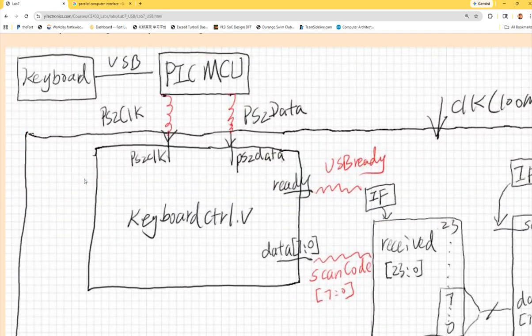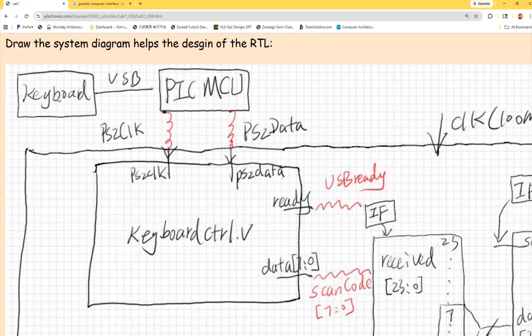If you look at the diagram, it will probably make it a little bit clearer. So the keyboard directly connects to the FPGA through the USB, and then interfaces with the PIC microcontroller, and then these are the two physical pins of the FPGA. Okay? Is there a desktop involved in this experiment? No, it's directly keyboard to the USB, right? To the USB of the Basys board. So it goes this way, and these are the two physical ports already, right?